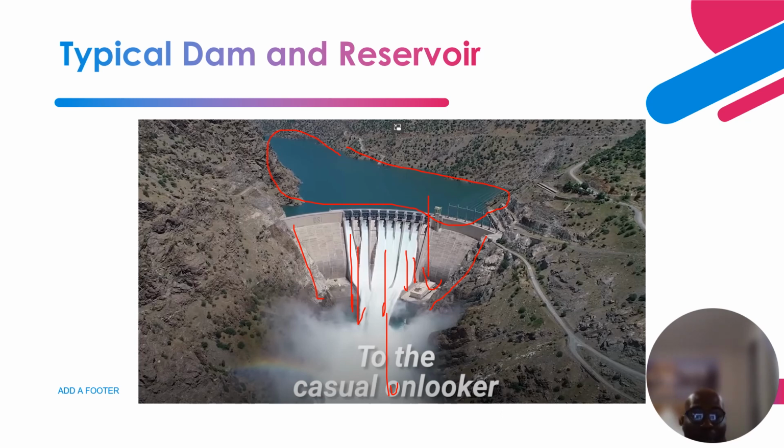So periodically they flush the sediments out, utilizing these big, fast sluice gates that are located on top here. Instead of the water going through the turbine, they divert it to another gate where it flushes all the sediments that are located behind the dam.